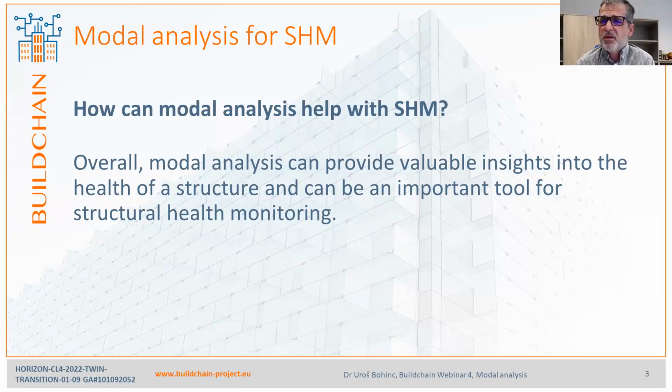Overall, modal analysis and the knowledge of how the structure behaves dynamically to external loading tells a lot about the rigidity of the structure, the way the structure functions, and by monitoring, for instance, changes in natural frequencies of the structure alone, we can say something about the evolution of damage.